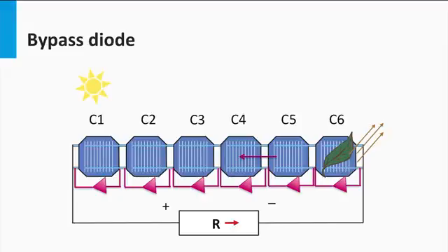In this figure you can see bypass diodes included in the electric circuit. A diode, as discussed in week 2 and 3, blocks the current in a direction when it's under negative voltage, but conducts a current when it's under positive voltage. If no cell is shaded, no current is flowing through the bypass diodes. In the case that one cell is shaded, due to the biasing of the other cells, the bypass diode starts to pass current through. As a result, the current can go around the shaded cell and the module can still produce the current equal to that of a non-shaded single solar cell.